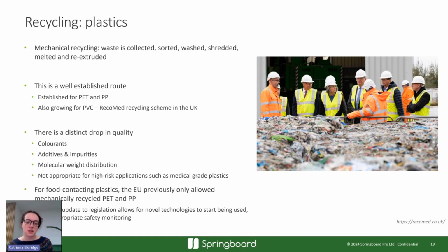On some later slides, we'll talk about the drop in quality in a bit more detail, but there is a distinct drop in quality through this recycling process. And that's because you have things that have been added. You have additives, you have impurities, you have colorants. If you end up with a lot of blue or green or just a mixture of colors coming into your input, your final product is probably going to have to be either gray or you're going to have to dye it black. And the fact that you can't make your plastic whatever color you want is a drop in quality. It leads to a drop in price.